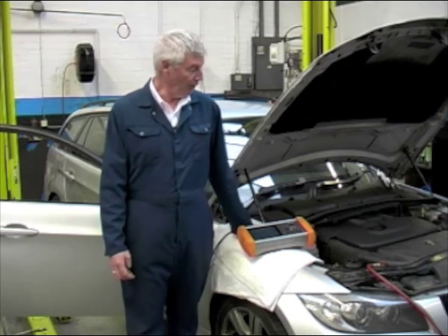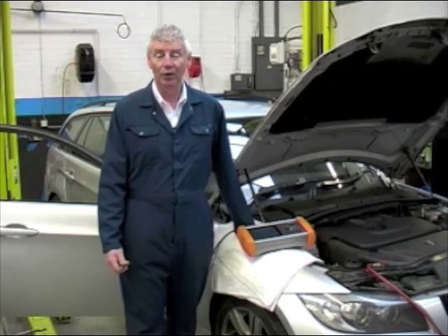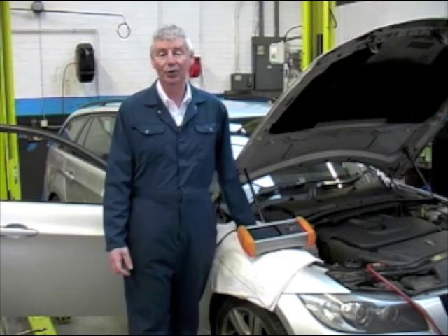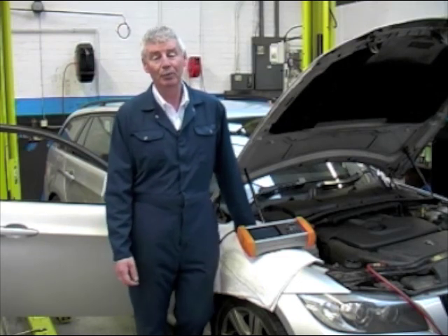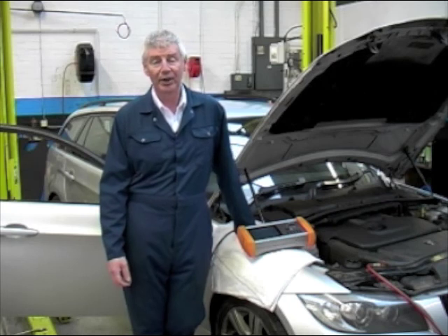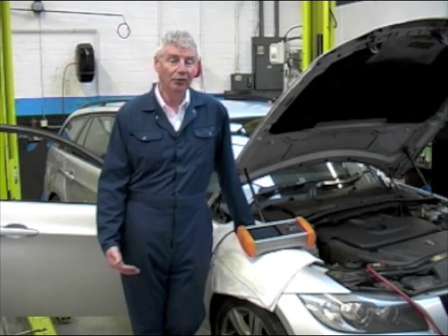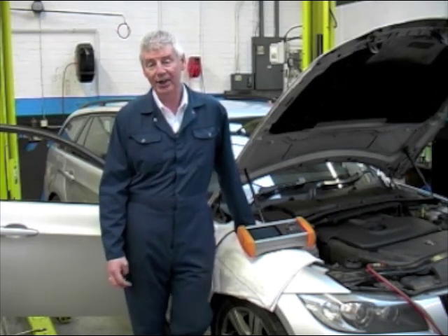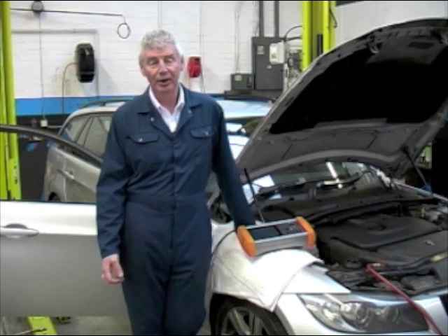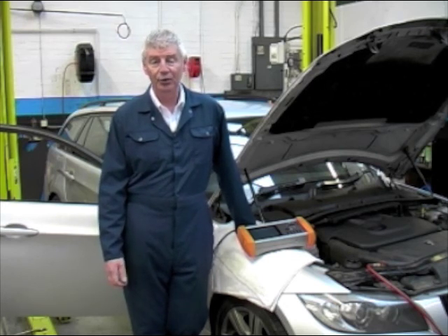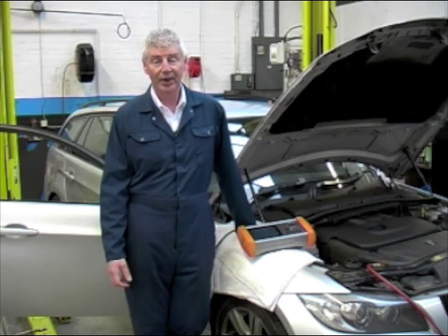But it just goes to show that the fault codes don't always have to be logged in the climate control system ECU. It could be in other areas or other ECUs on the vehicle, so it's worthwhile checking through, running a short test if that's available on the scanner for that particular vehicle, and removing those fault codes. And of course, check your live data.